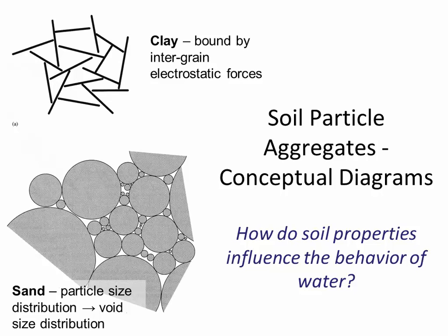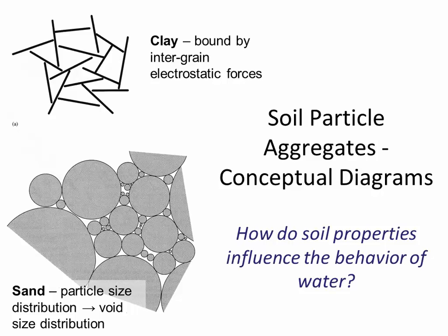So what this figure says is that if you look at the soil, there's only a few of these voids that are really big, not very many of them. There's only a few cases, maybe 1, 2, 3, 4, where the void size is really small. The majority of the time, it's a medium-sized void. So it's not all the same size void. There's a whole spectrum of different void sizes there. And that's going to be important when we talk about soil moisture.